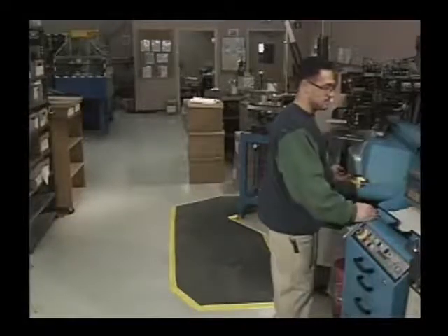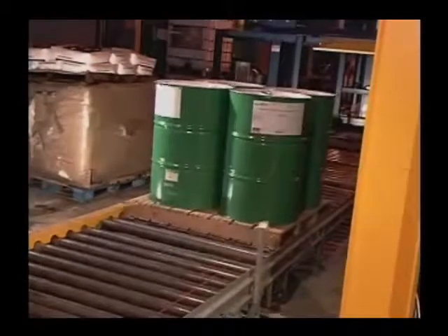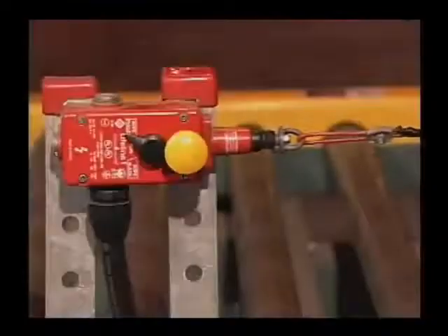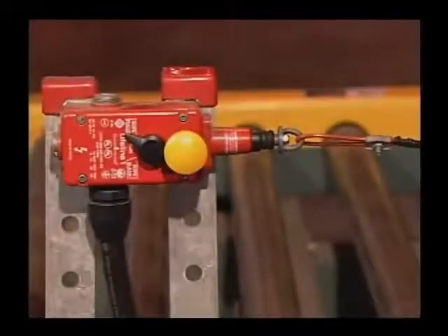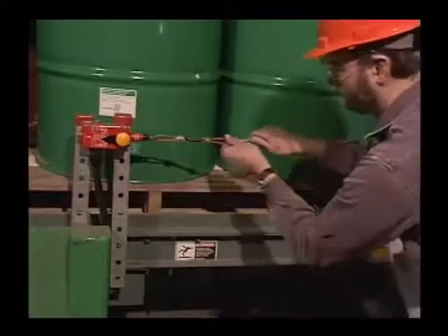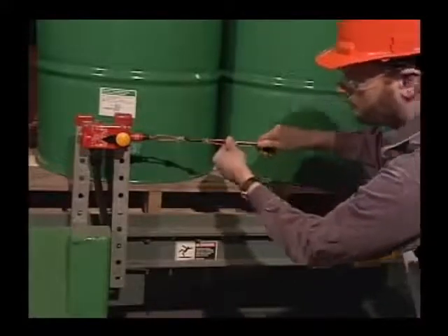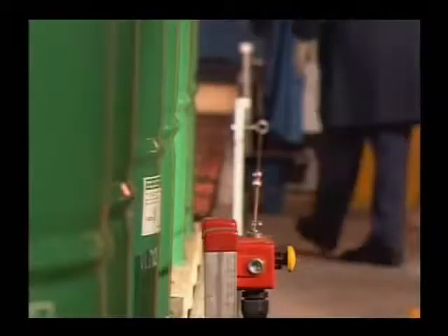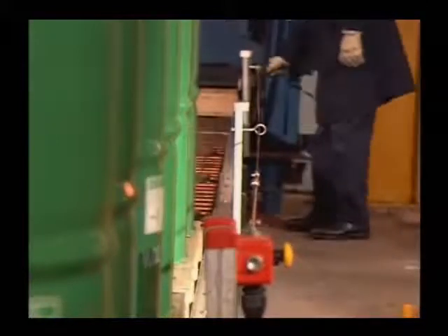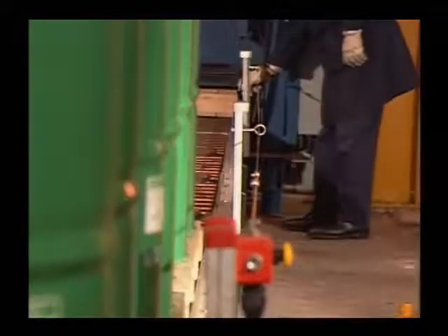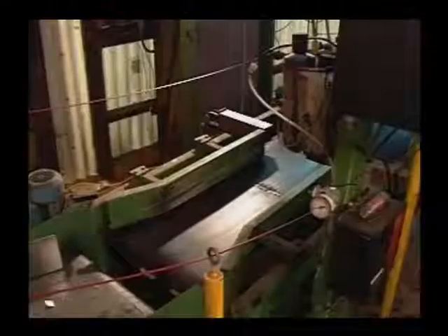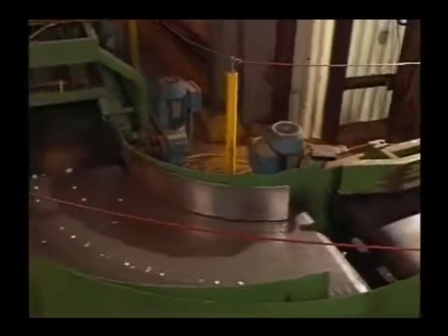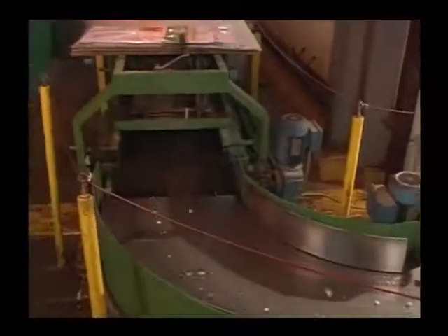Pressure-sensitive trips often use wire cables and safety lines. If a worker touches one of these lines, it triggers a switch that stops the machine. In order for trips to be effective, the cables must be taut and set so that they will stop the machine at the slightest pressure. Because the cables can cover a wide area, pressure-sensitive trips are ideal for long expanses, such as conveyor lines. By routing cables through eyelets, trips can also be used to protect unusually shaped machine perimeters.